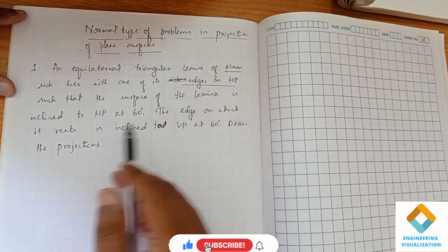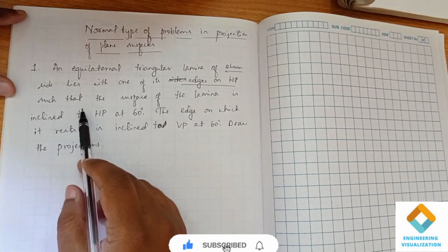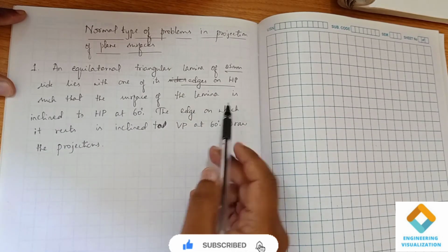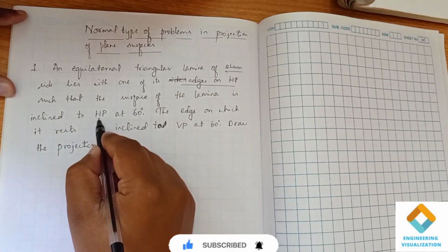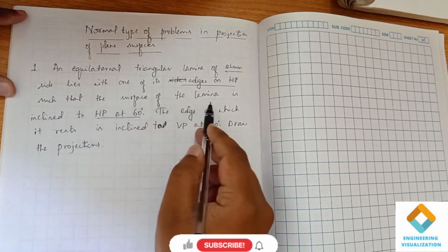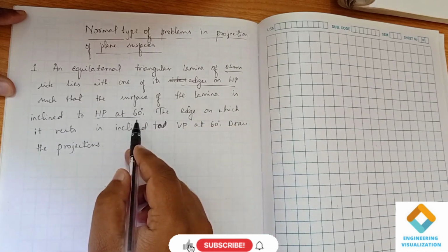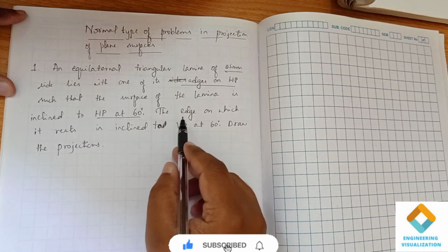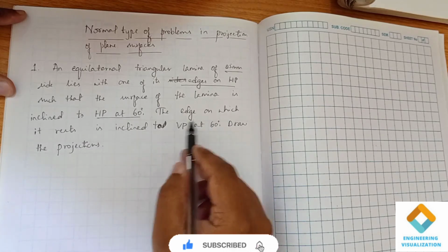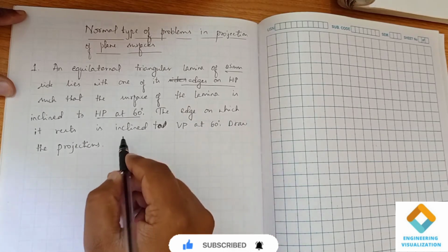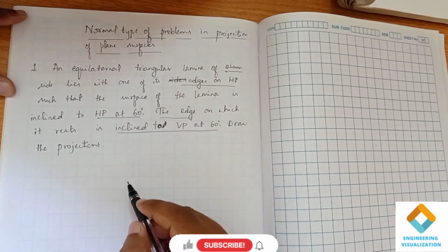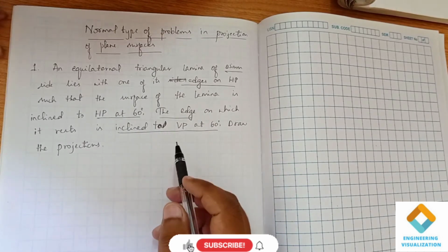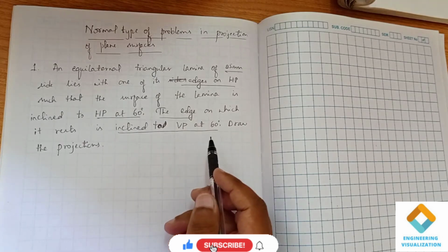Okay, now you see, proceed with the question, such that the surface of the lamina is inclined to HP at 60 degree. Herein the surface of the lamina is inclined to the HP by 60 degree. That's the first inclination to HP. Now the same edge on which it rests is inclined to VP at 60 degree. That is, the same edge which has been inclined to the HP, we are inclining again to the VP by 60 degree.